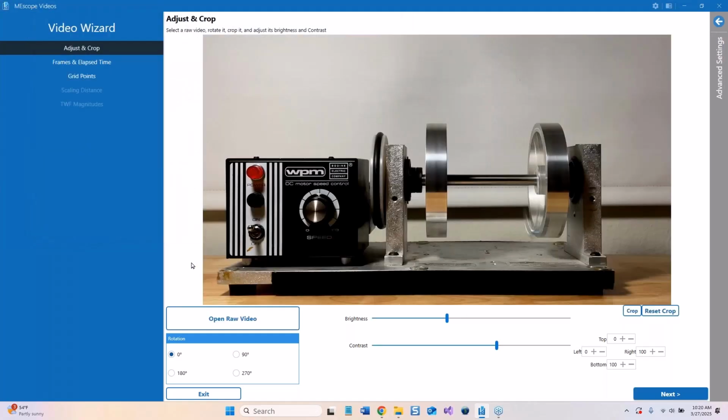So there it is, the same one that Sean was showing you in his presentation. And you can see that we put different unbalanced screws here on the inboard and the outboard rotor to artificially create unbalance in this machine. And then we can take the ODS data from the video and do further processing of the raw data. We can curve fit it and get mode shapes and all kinds of things. So we're just going to do the simple stuff today.